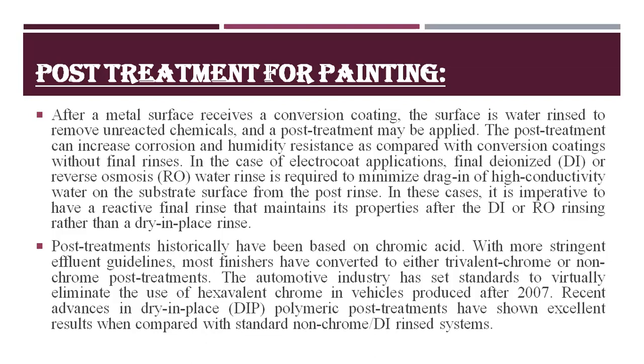Post treatments historically have been based on chromic acid, but with more stringent effluent guidelines, most finishers have converted to either trivalent chrome or non-chrome post treatments. The automotive industry has set standards to virtually eliminate the use of hexavalent chrome in vehicles produced after 2007. Recent advances in dry in place polymeric post treatments have shown excellent results when compared with standard non chrome or deionized rinse systems.